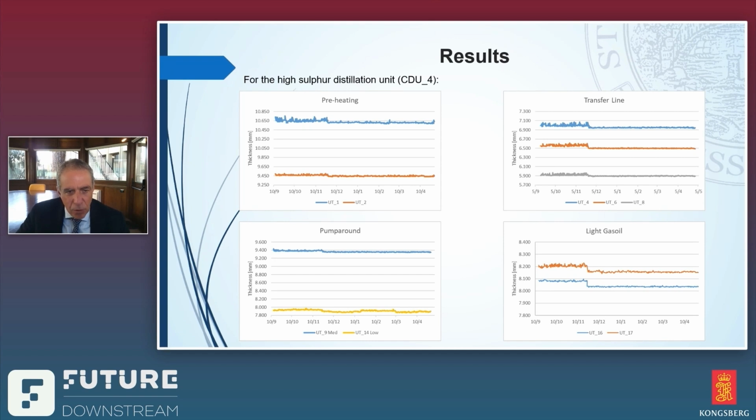And so we had the equation of how the corrosion rate is going. This is the trend, because the corrosion rate probes are online and sent to the DCS, so we can trend the thickness. We can see that the measurements are always very close. So there was not a big problem concerning corrosion, even because we used, as I said before, inhibitors.